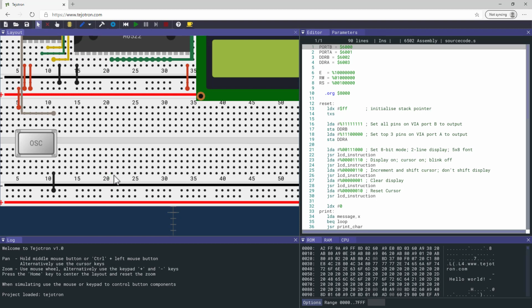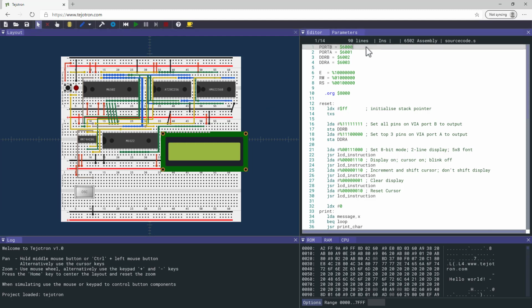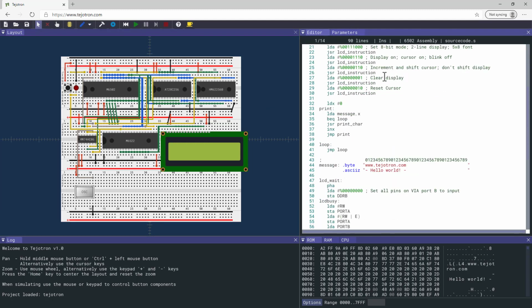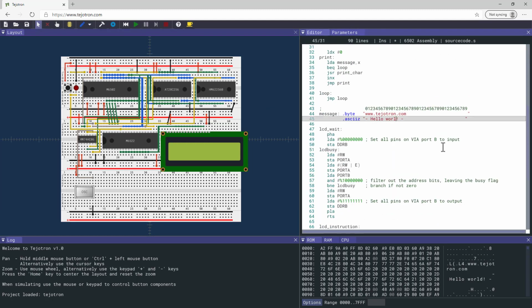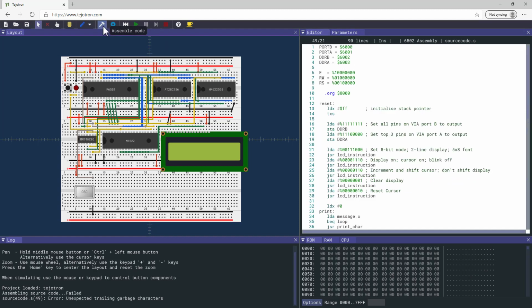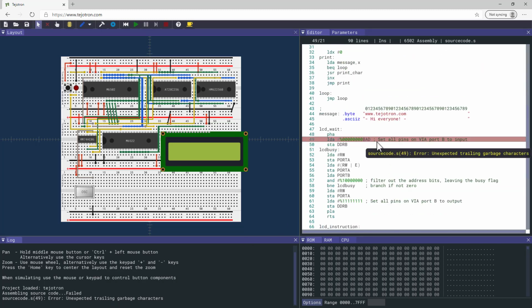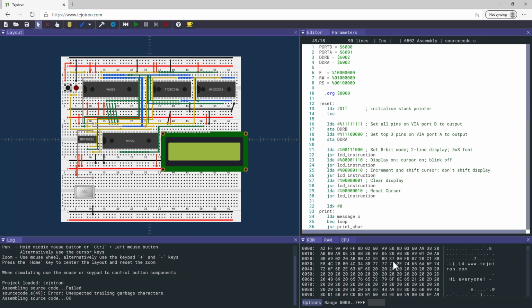The editor window allows you to edit the source code that can then be assembled as a binary image into the ROM. Pressing the hammer toolbar button will run the assembler. If the source code cannot be assembled, the ROM will be cleared and issues are reported. It is possible to edit the contents of the ROM directly, but running the assembler will always overwrite any changes.